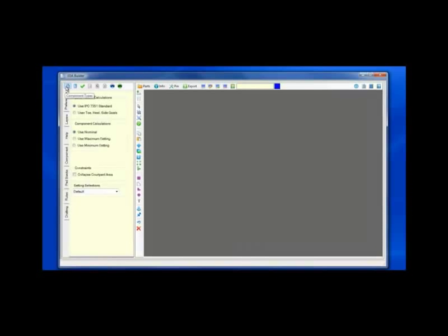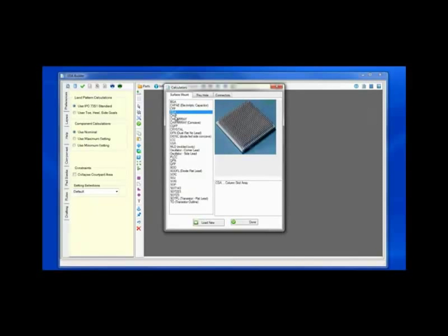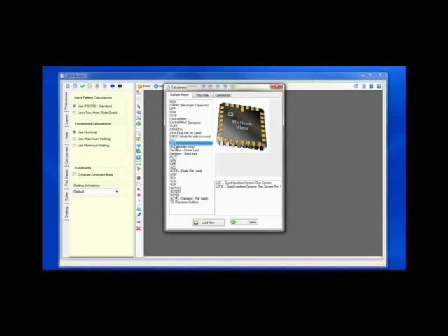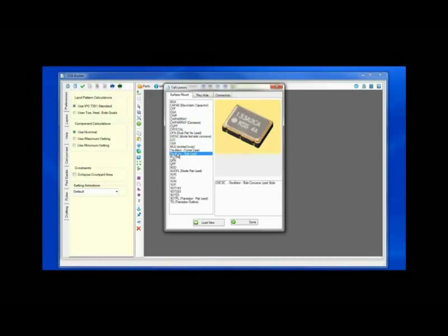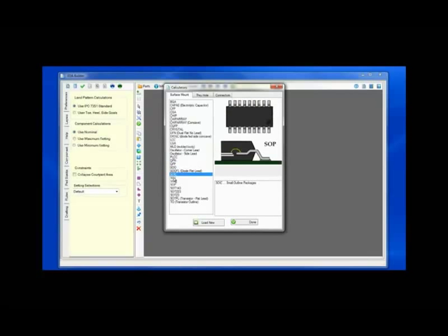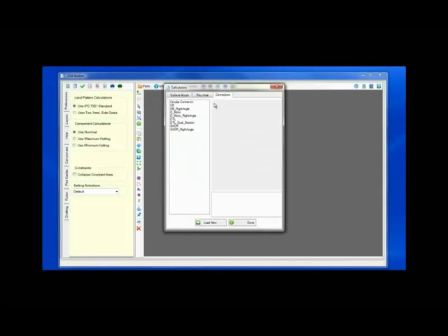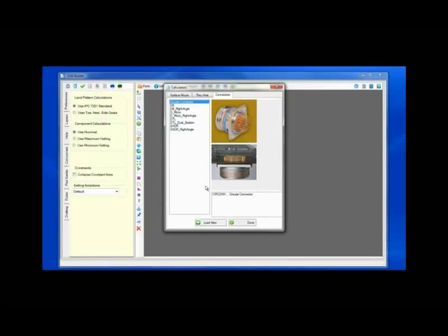In the footprint builder, we have a host of calculator types, including caps, BGAs, CGAs, chip array, CQFP, crystals, diodes, LCCs, LGAs, molded, oscillators, PLCCs, QFNs, SODs, SOICs, SOTs, and TOs, plus the through hole and the connector calculators, including DB, right angle, DTL, shrouded headers, and a host of calculator types coming online.